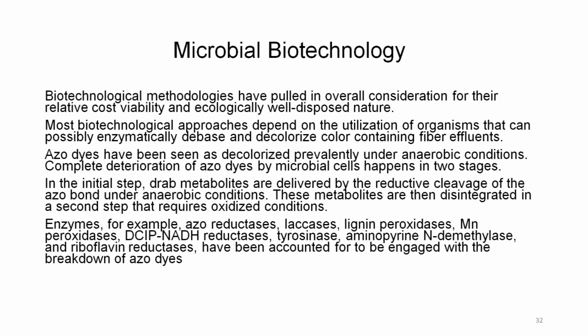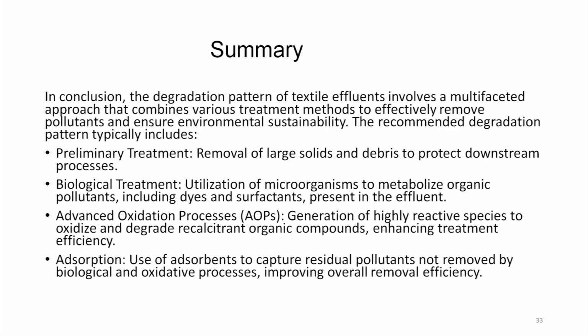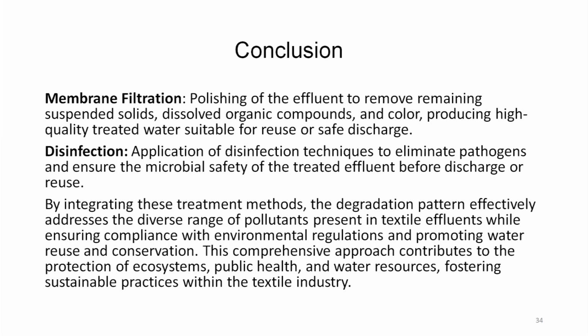Moving on to microbial biotechnology, we have dealt a lot in detail with this, and we know that enzymes, for example azoreductase, laccases, lignin peroxidases, manganese peroxidases, reductases and tyrosinases, are all responsible for the breakdown of azo dyes with the help of these microbes. In conclusion, we can say that primarily the preliminary treatment, biological treatment, advanced oxidation processes, adsorption, membrane technology and disinfection are all very much responsible.